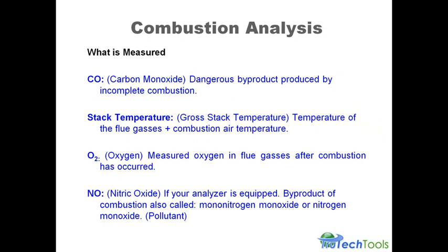If the combustion air comes in at 70, obviously it's got more heat in it than if it comes in at 0, right? Because instead of heating up 70-degree air, we're heating up 0-degree air. You know, that air is colder, right? We're running, 79% of that's just nitrogen going through the flue gases. So, you're bringing air from outdoors and you're heating that air up. Now, you've got to realize that the specific heat of air is 0.24. So, I mean, it takes very little energy to raise that 0-degree air up to the stack temperature.